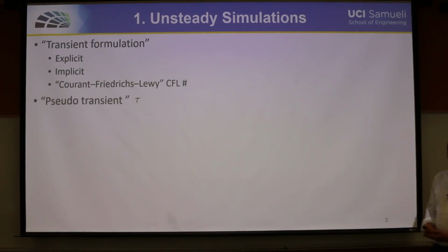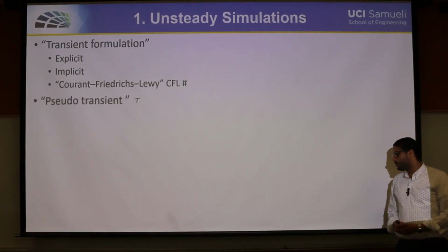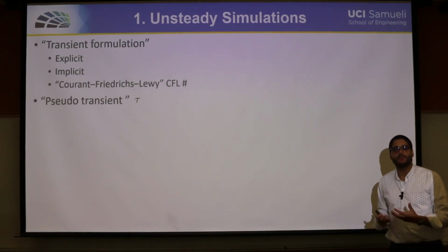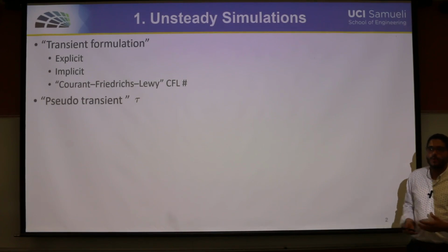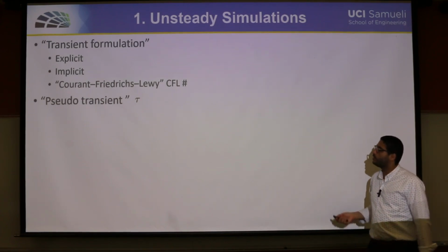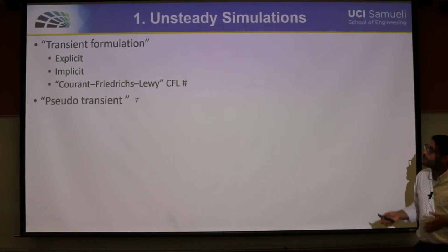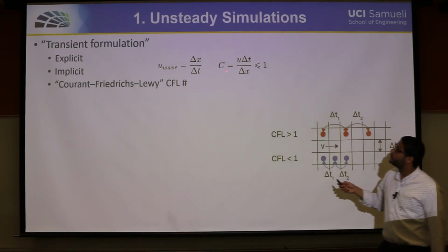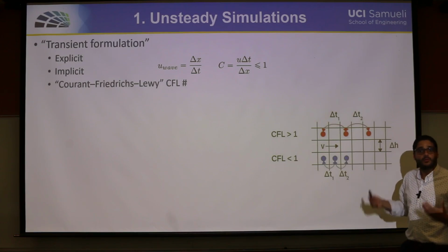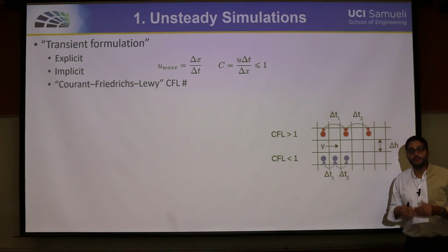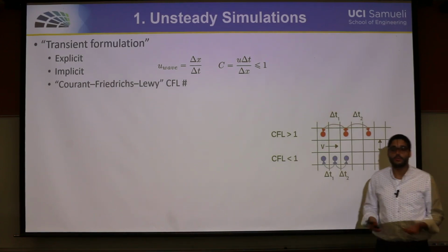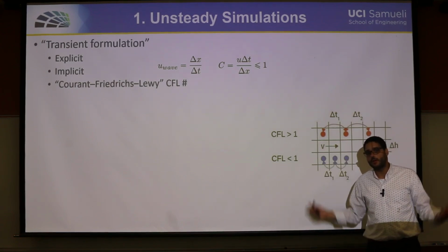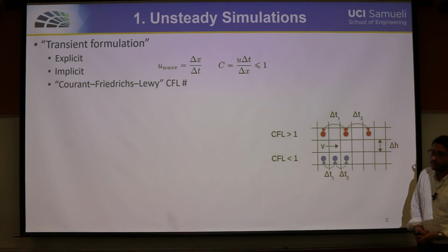The pseudo-transient, when we talked about it a little bit last time, we said that Fluent was trying to address the restrictions over the CFL that force you to select specific delta t's, which could be a very small delta t, and you might not have the luxury to stay for a month or a week or even a year doing your CFD simulation.